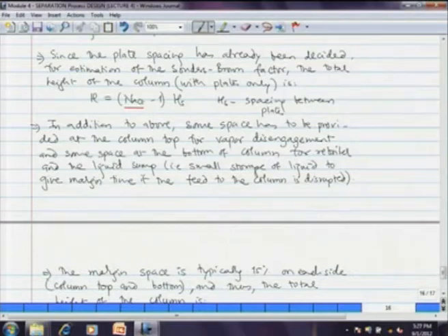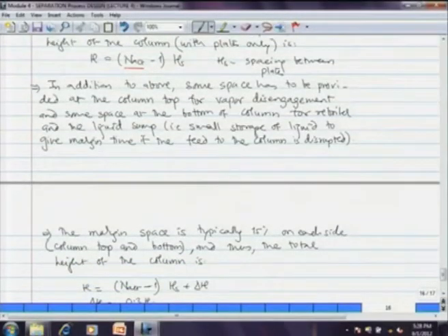Why? Because having that reservoir is essential so as to give some kind of a margin for column operation in case the previous column or the previous supply is disrupted. So, instead of feeding directly to the bottom, you need some liquid reservoir. That storage also requires space.